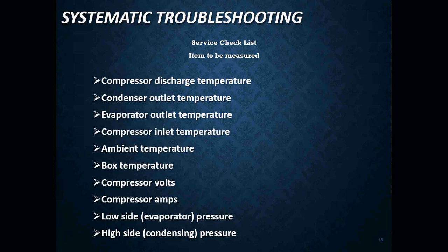A service call is going to require you to take temperature readings, voltage readings, amperage readings, resistance readings, superheats, subcoolings, all of those things. Okay? By having a good organizational skill, you are going to solve even the toughest problem more quickly. Okay, one way to be organized is to have a checklist, kind of something like you see here. Okay? We need to make sure that we're checking a lot of these things.